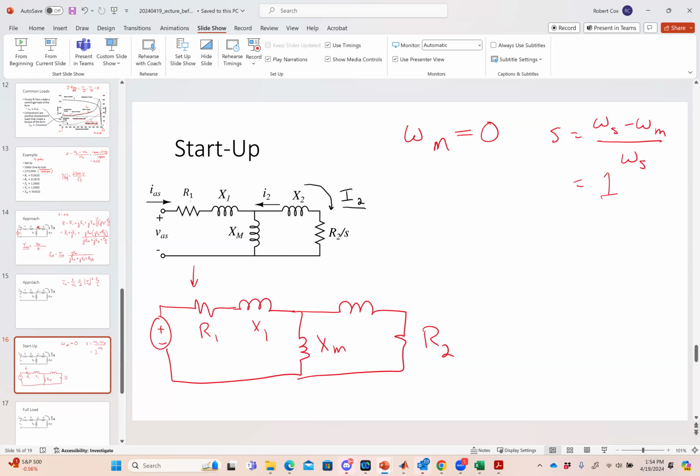Now, if I told you, and this is a good question to remind ourselves, back in the case of transformers, you probably don't remember this that well, but if I have these values of leakage and these resistances, those resistances are parasitic. They're the resistance of the windings. So resistance of the windings should be small, ideally, or else it's probably a very inefficient machine, making a lot of heat.